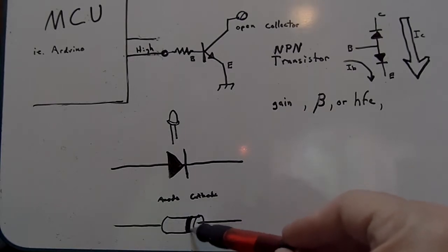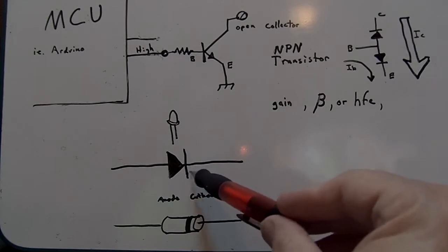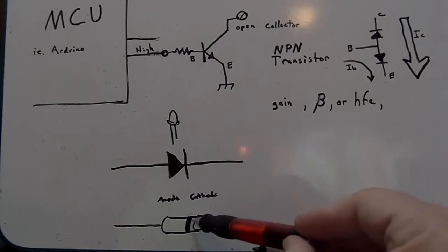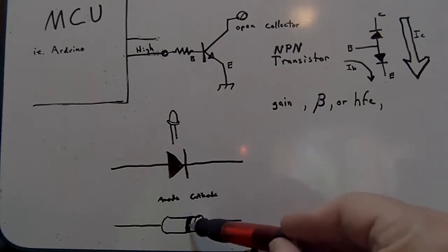And usually there'll be little cylinders, like a resistor. You have a band on the one end that'll mark the cathode end. It's usually marked as a band. And it could be white with a dark band. Normally they'll be black with a silver band.